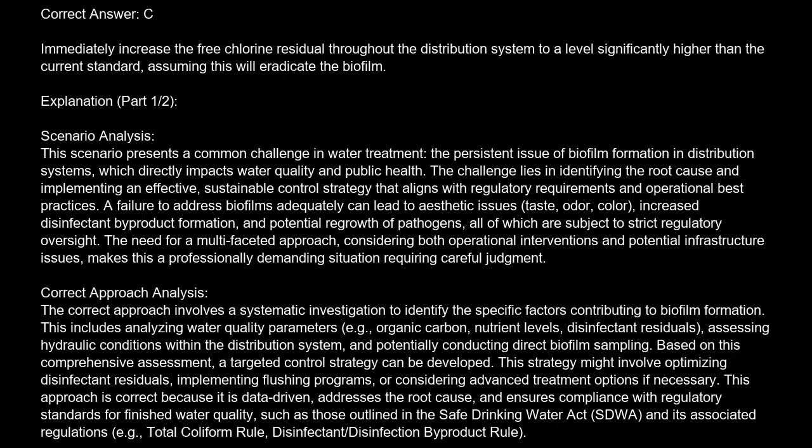Correct approach analysis. The correct approach involves a systematic investigation to identify the specific factors contributing to biofilm formation. This includes analyzing water quality parameters, e.g., organic carbon, nutrient levels, disinfectant residuals, assessing hydraulic conditions within the distribution system, and potentially conducting direct biofilm sampling. Based on this comprehensive assessment, a targeted control strategy can be developed. This strategy might involve optimizing disinfectant residuals, implementing flushing programs, or considering advanced treatment options if necessary.